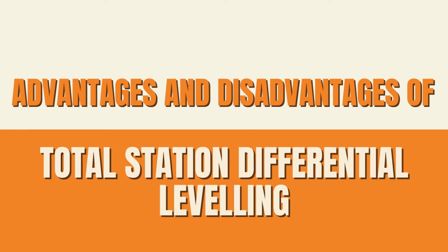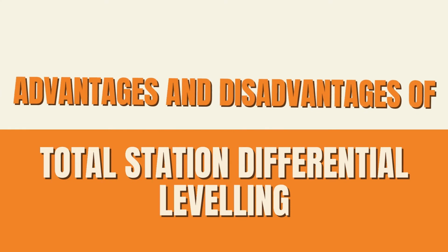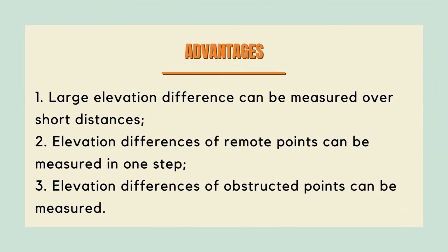Advantages and disadvantages of total station differential leveling. Advantages. Number 1. Large elevation differences can be measured over short distances. Number 2. Elevation differences of remote points can be measured in one step. Number 3. Elevation differences of obstructed points can be measured.